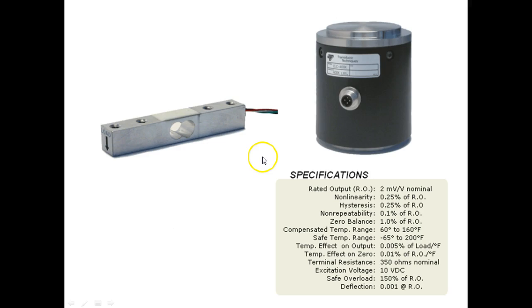Now that's just these strain gauges right here. This load cell right here, though, it puts out 2 millivolts per volt. And I don't know if that's this one or not. But look at the size of the thing that this measures. When this truck pulled up on there, it would actually cause that thing to squat down and get fatter, and then the load cells, the strain gauges, measure that. It always amazed me.